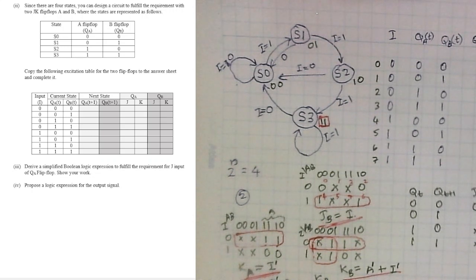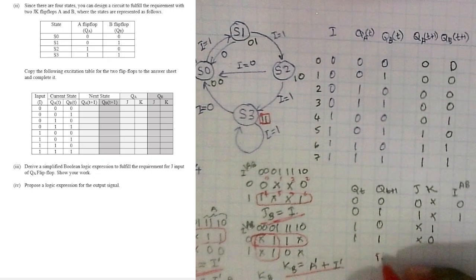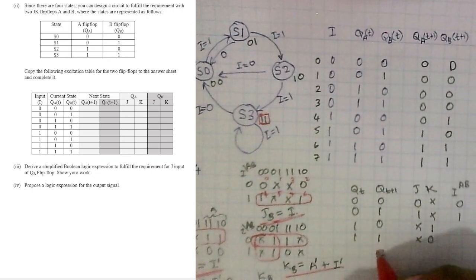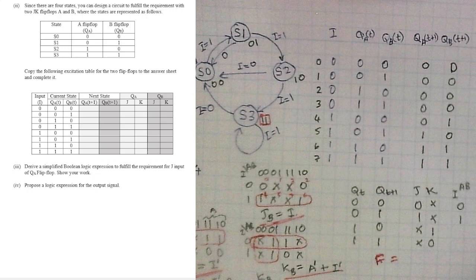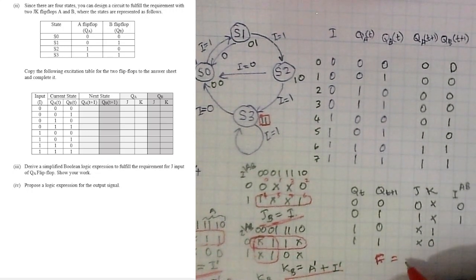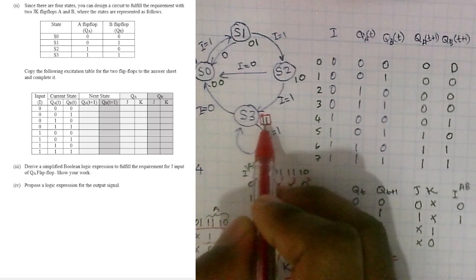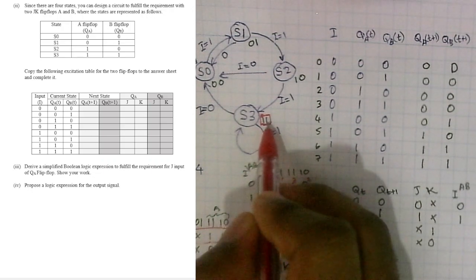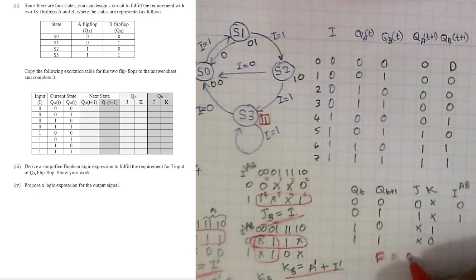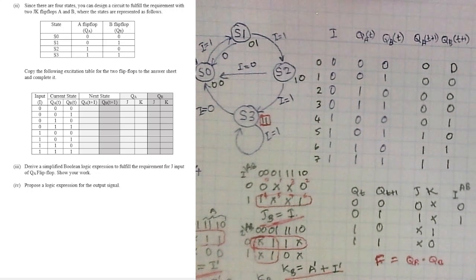So we can just write output signal. Let's say it's F, okay. Pen is not perfect. Anyway, so F is just both of QA and QB should be 1, right? So it's QA, and so I just put this dot here, QB. Okay, so we have a output signal as well. So let's see the timing diagram of my implementation and how it works.